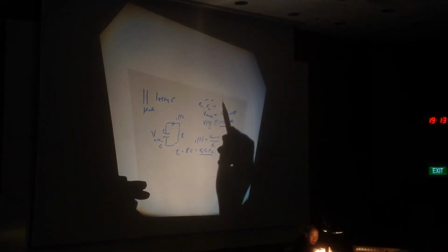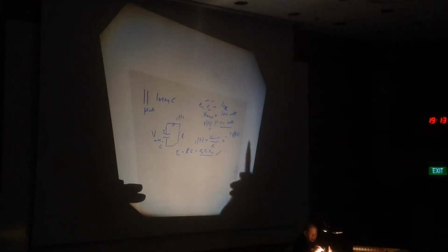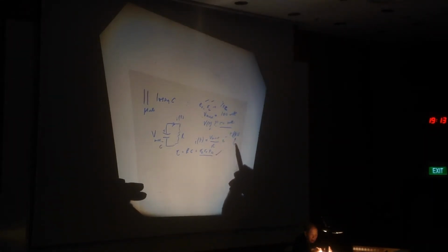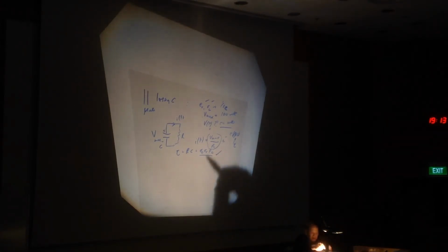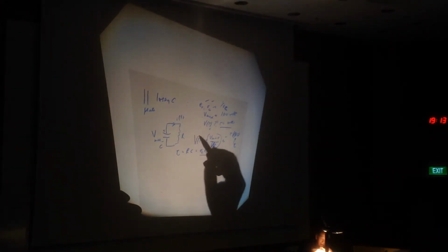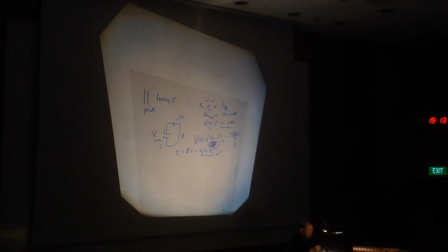So therefore this is the same as 1 upon rho C. You can calculate the time constant, tau here. You can calculate when it becomes half. Or if you want the maximum voltage, the voltage will be decaying exponentially, and it can be found. But you can see this is where this comes in. So you don't even have to calculate R, you don't even have to calculate C, because the product you know already.